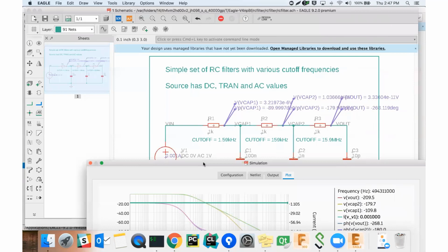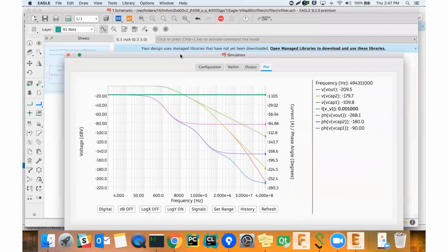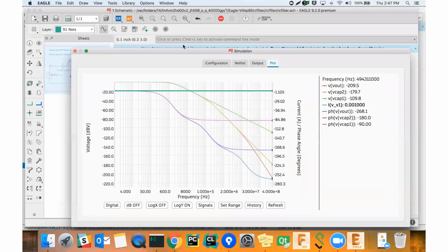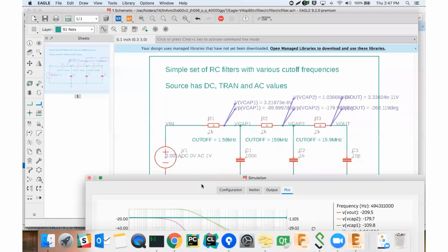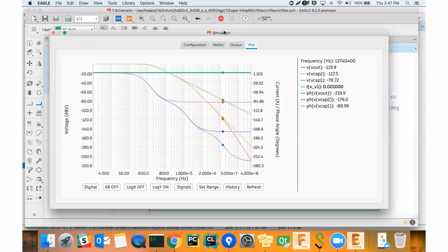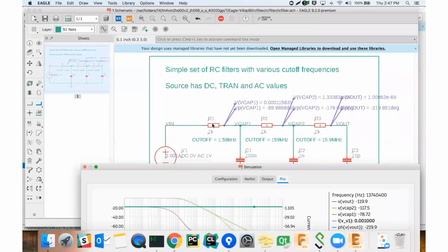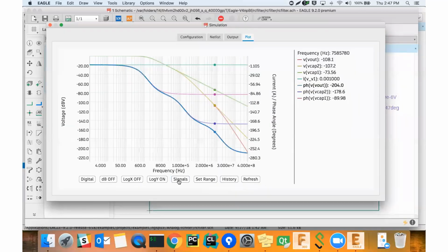So if I simulate my input as 1 and my output says 10, then I know whatever my input is, the output will be 10 times greater. So 1 is kind of used as, let's say, a pro tip, just as a simple way to scale your value. So I'll leave it as 1, and we expect that over time, this input signal will actually drop off. So what I'm going to do is use our signal chooser.